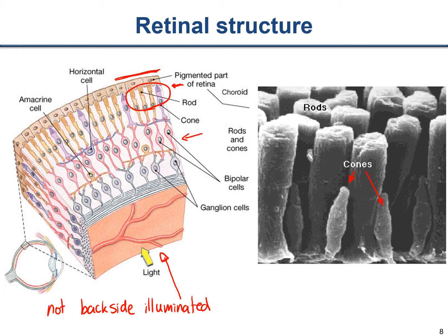Now we typically will use a backside illuminated system where we flip the structure around and we have the light hit directly the photodiodes from the back, and then we can fill up the top with all sorts of interconnect without having to worry if the light can actually reach the photodiodes or not. Okay, and this was a way that engineers were able to improve the low light sensitivity of cameras, in particular in smartphone cameras and so on. These are finally making their way into digital SLRs now.